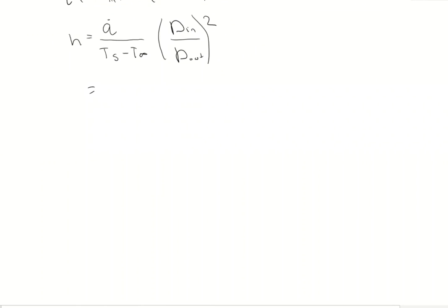Okay. So this 60, we'll do a little unit change there. And then again, our 50 is that surface temperature we're trying to get. So essentially, we're trying to create the conditions of h such that this outer layer will be 50 degrees Celsius, minus 23. And the units for this are actually delta degrees Celsius.